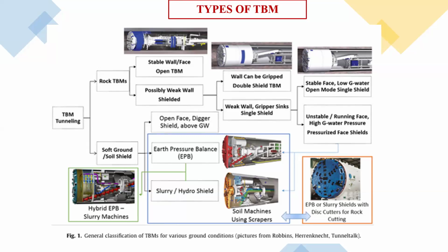Now it can happen that the excavated material has a very low specific gravity or is very bulky, and it cannot apply the sufficient thrust that is expected from the ground. So at that time you use some types of additives or some sort of polymers to make the excavated material of a heavier specific gravity.